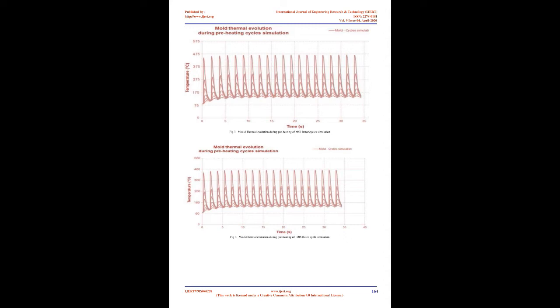Clamp pressure. The only reason to have clamp pressure is to keep the mold closed against injection pressure. Therefore, the amount of clamp pressure required is based on the material being molded. The easier flow materials require less injection pressure, thus they require less clamp pressure. Conversely, the stiffer flow materials will require more injection pressure, thus more clamp pressure.